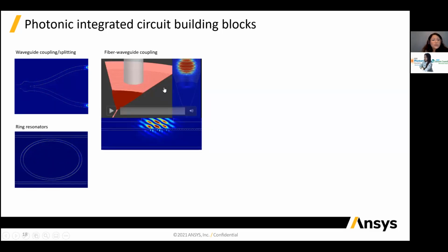And now this is another example of a building block where you want to bring the light into the chip and then take the light out from the chip, right? In order to do those, you might want to use a grating coupler. I would like to show you the top view and the side view of what's happening here when the light is falling on the grating coupler. It goes in, and then you see there is a grating which is very carefully designed. The light falls onto it, and then some of it gets coupled and some will pass.